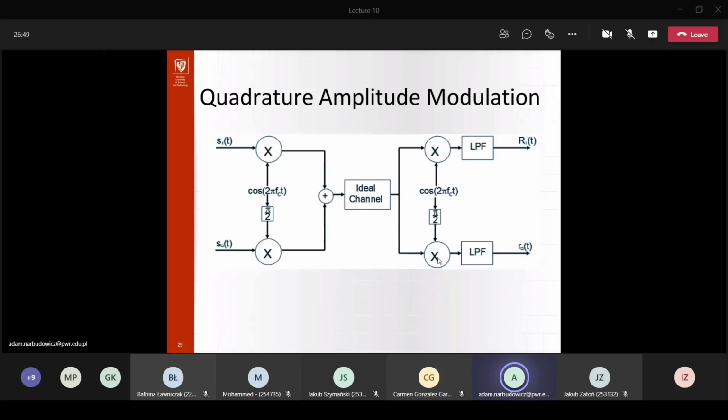So you send a previously agreed sequence of symbols, which the receiver knows the meaning of. It uses those symbols to correct for this phase shift, to rotate the QAM diagram back to the position it was intended to be, and only then, when it is so calibrated, can the information be transmitted.